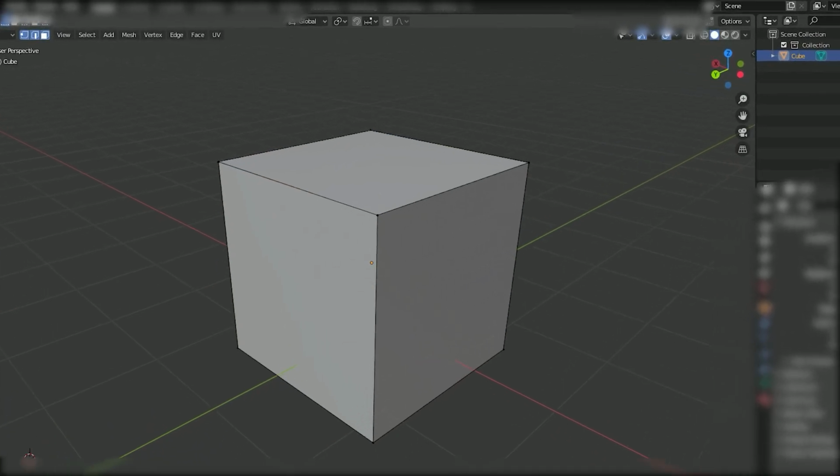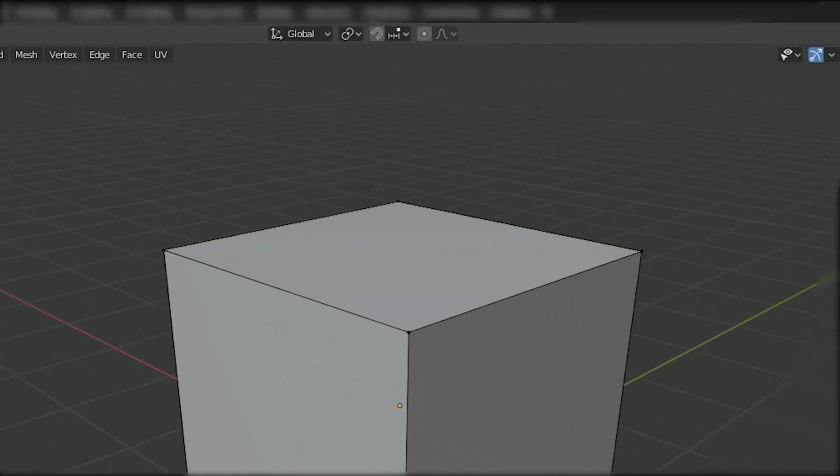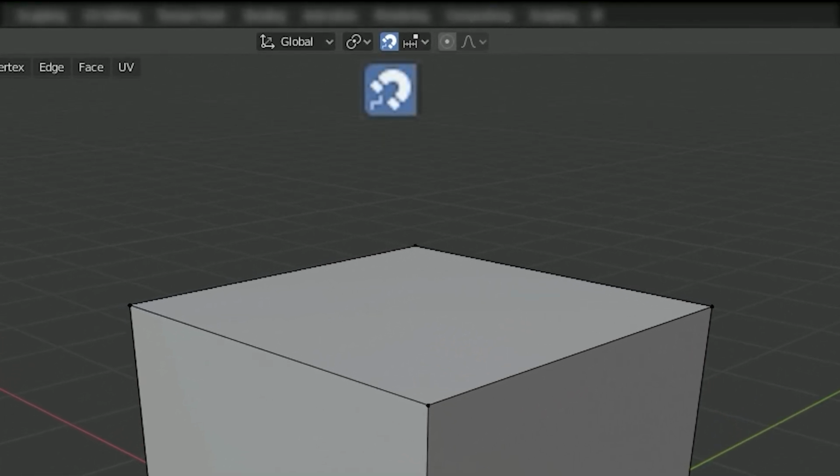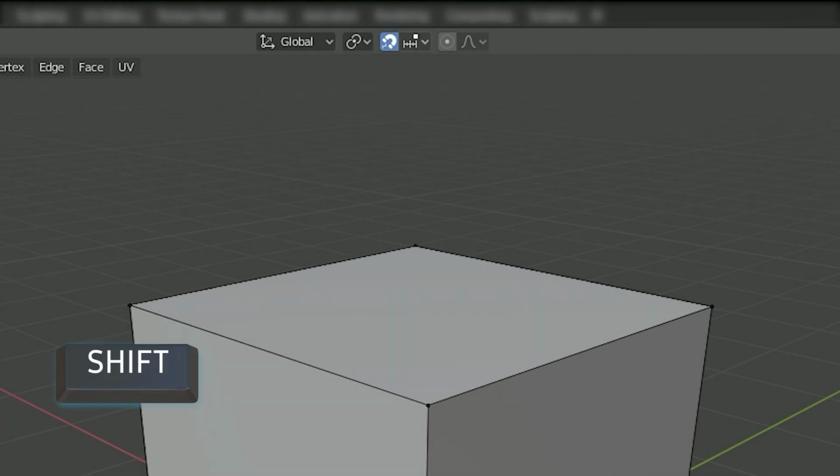First off, you have to enable snapping by either selecting the snap button, which looks like a magnet in the top center group of icons, or by pressing shift plus the tab key. By default, snapping is not enabled, unlike in SketchUp where you can't turn it off, which I did find annoying at times when working on more complex, non-linear models, as it kept trying to guide my positioning.